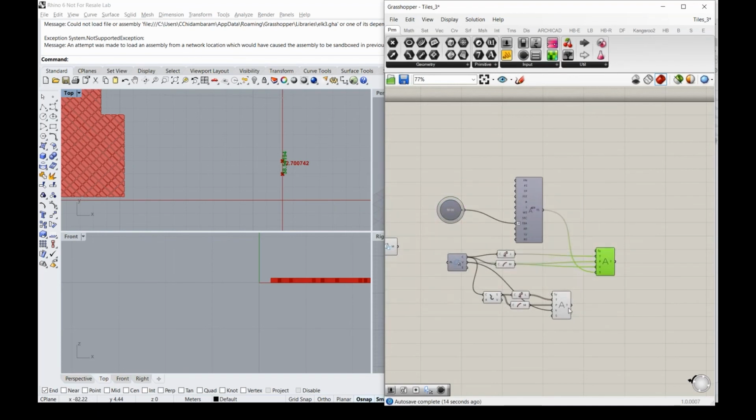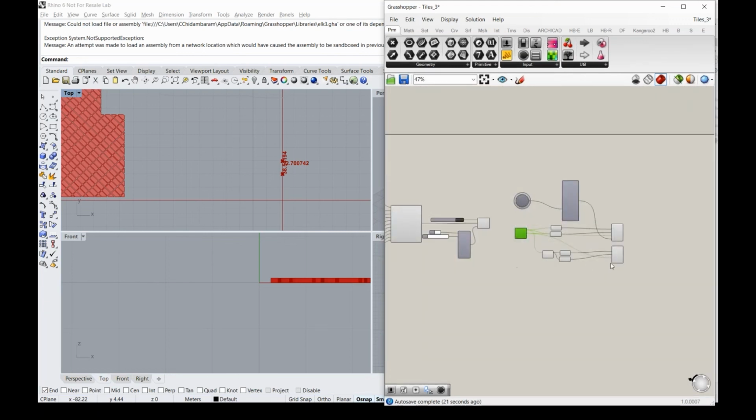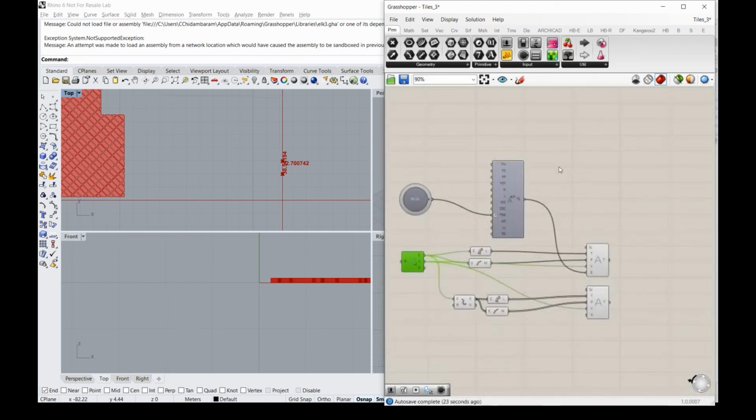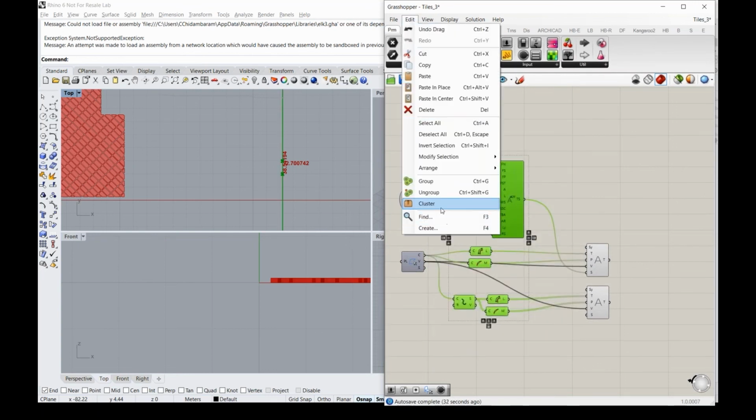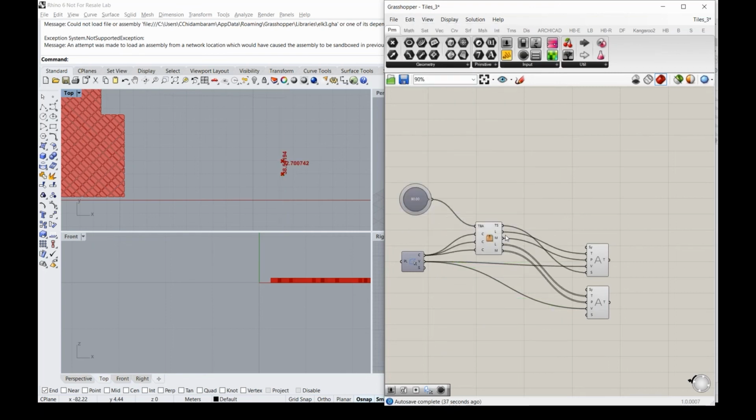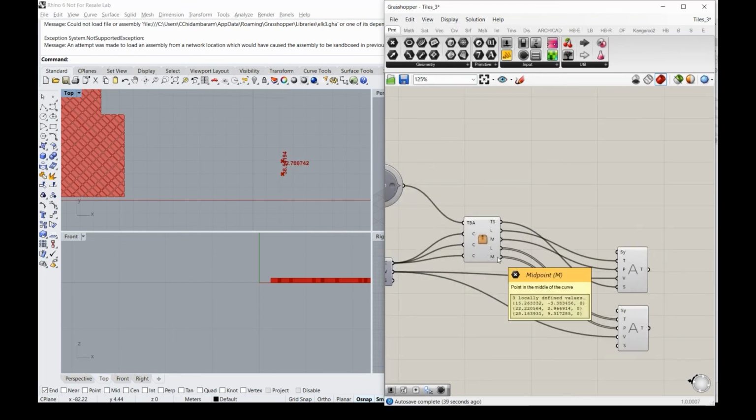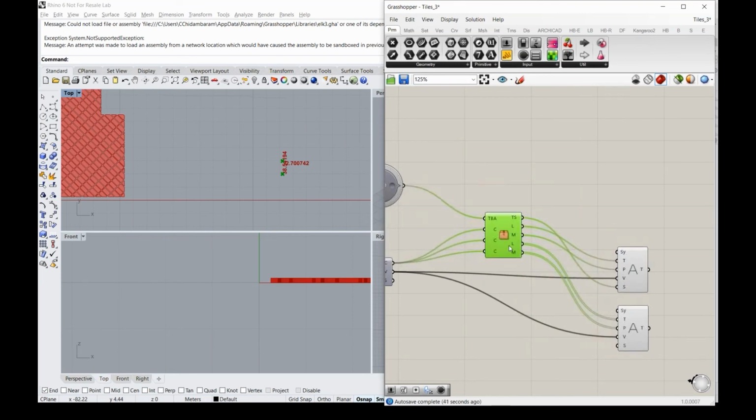So what I can do is I will move this. I'm going to show you how to create a cluster. So how do I create this kind of thing and distribute to people? So I select this. So I select this one and I will go to my edit menu and there's this cluster. So if I say cluster, you can see everything I selected will be added this way. So it is like you're passing this information and it will output this information.